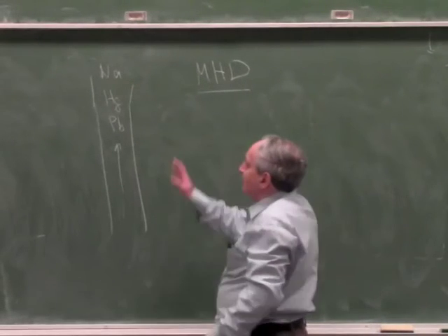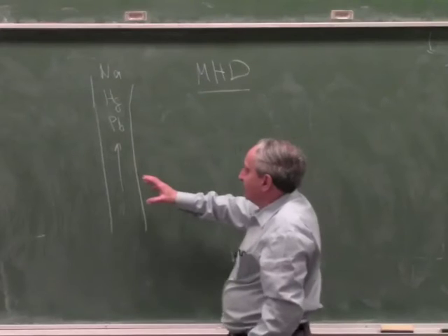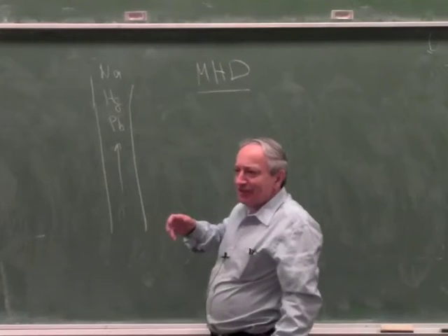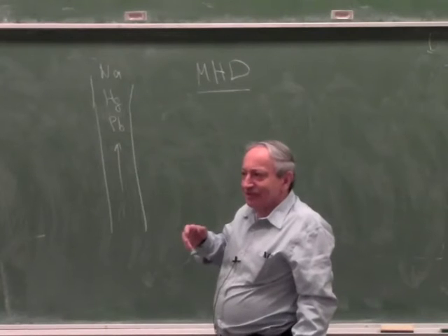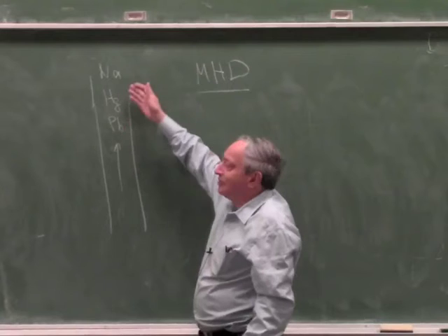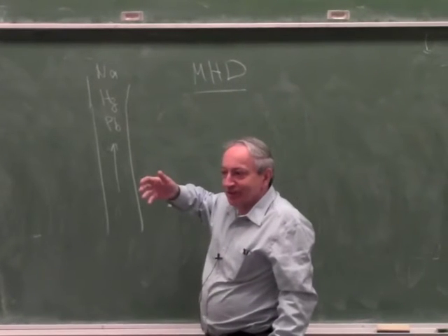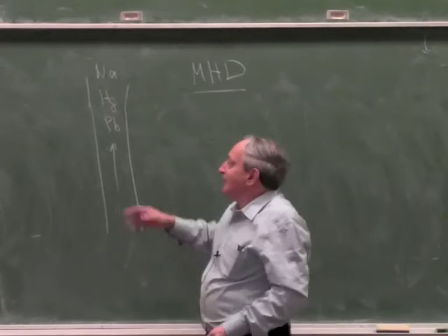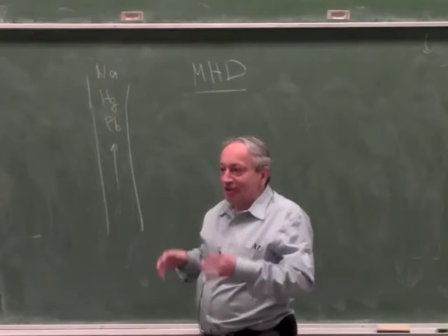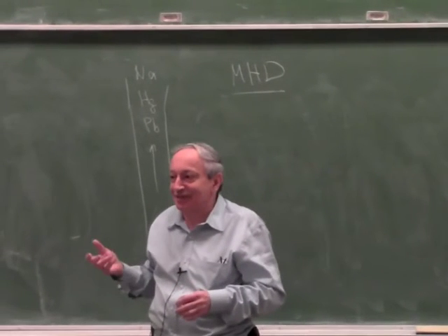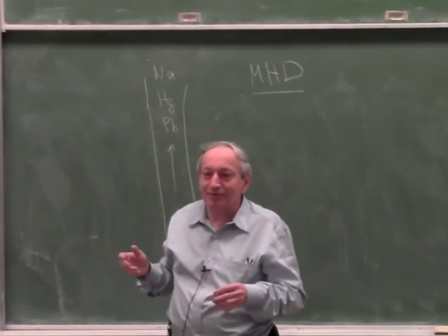So you want to pump it in a pipe, and normally you'll take this pipe and put a pump in it, and that is actually quite a nasty thing. Because first of all, these metals are hot, not mercury, but molten lead, molten sodium, these are very hot. Secondly, there's a problem with this, because once you stop the system, these metals which are hot will solidify, and the pump will be full of solidified metal. You wouldn't be able to restart it. Okay, so it's actually quite a big problem.